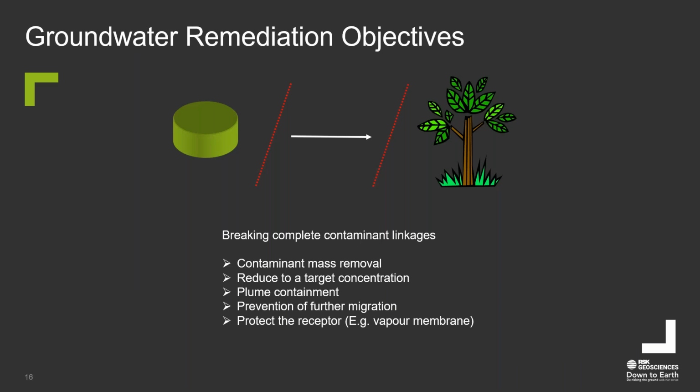It is also necessary to develop remediation criteria. Remediation criteria are site-specific measures against which you will assess compliance with the remediation objectives. They are usually quantitative and support the regulatory decisions as well. Therefore, the data should be collected during both the operation and validation stage to demonstrate that remediation objectives are met at a site. And also, it is important to back up your conclusion with the site-specific data. So you should collect multiple lines of evidence to demonstrate the meeting of remediation objectives successfully at the sites.